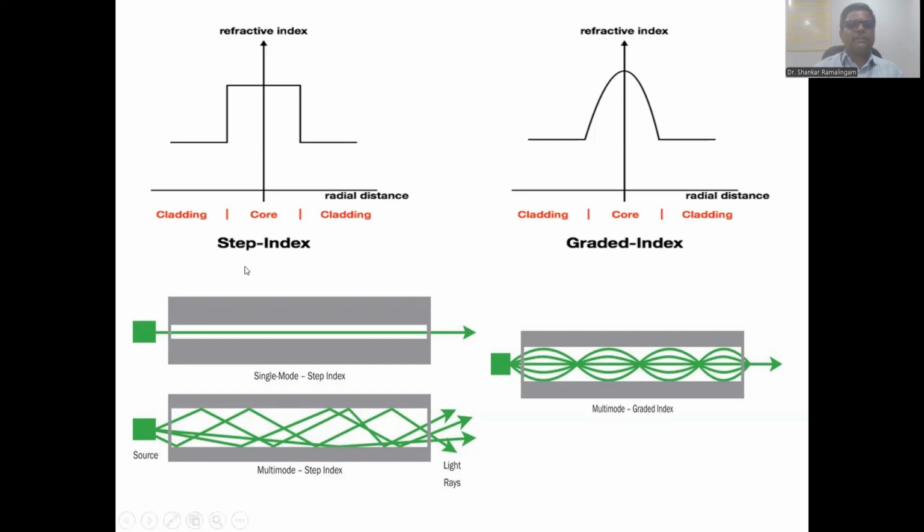In our step index optical fiber cable, the same is ensured, but in such a way that there is an impulse or sudden change in index between core and cladding. See, this is the value of the core's refractive index and this is the value of the cladding's refractive index. Okay, so this is plotted against the radial distance from the center to the outermost region of our optical fiber cable. So that is how it is for our step index optical fiber cable.